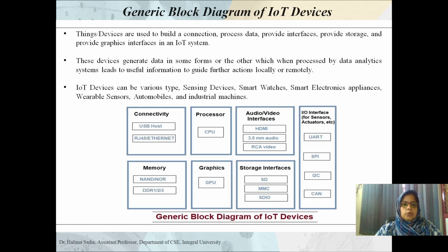UART is basically a universal asynchronous receiver transmitter. It is one of the simplest and the oldest forms of device to device digital communication. It is a protocol like SPI and I2C, but it is a physical circuit in a microcontroller or a standalone IC. It can be thought of as a computer hardware device for providing asynchronous serial communication in which the data formats and transmission speeds are configurable. It is a very important note that the data formats and the transmission speeds are configurable.